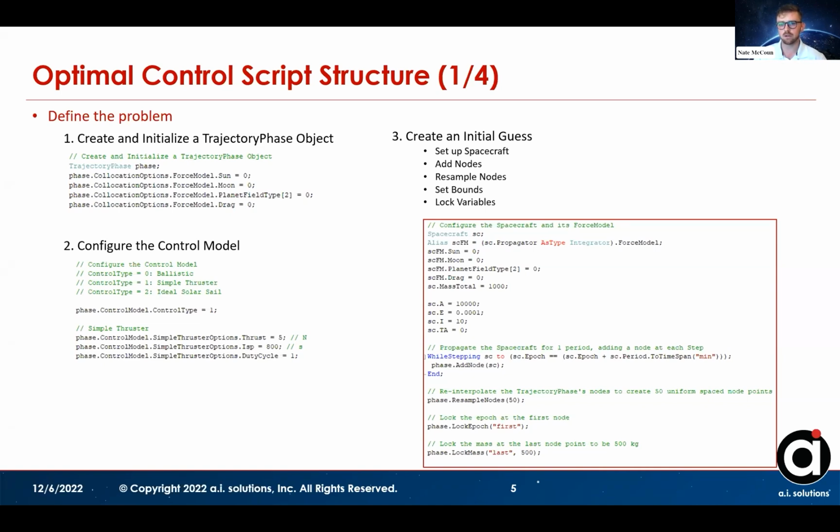There are other overloads which allow you to include barriers. So you can use independent uniform distributions with your user-defined barriers. An example of this might be placing 20 nodes in the first 30% of your trajectory and 10 nodes in the last 70% of your trajectory, or you can also concentrate nodes at the start or end of your trajectory.